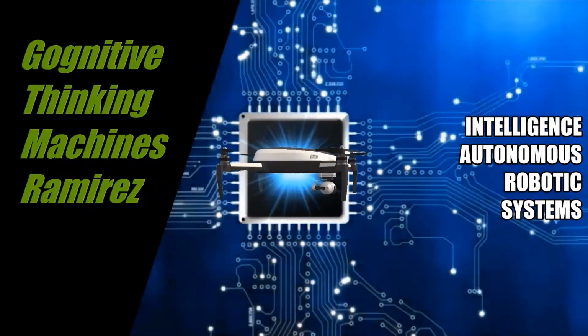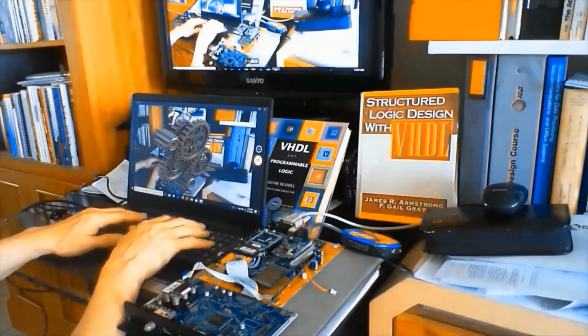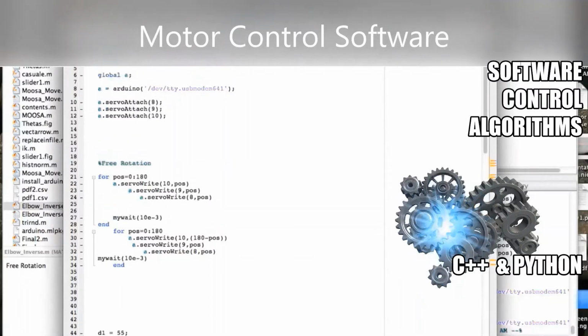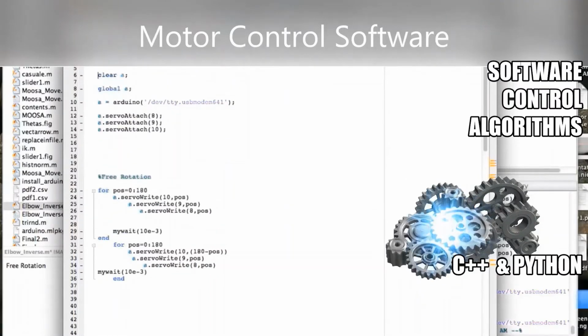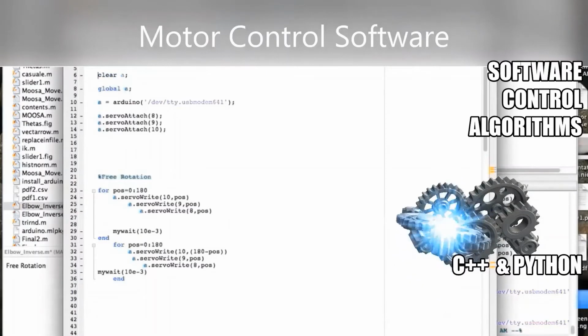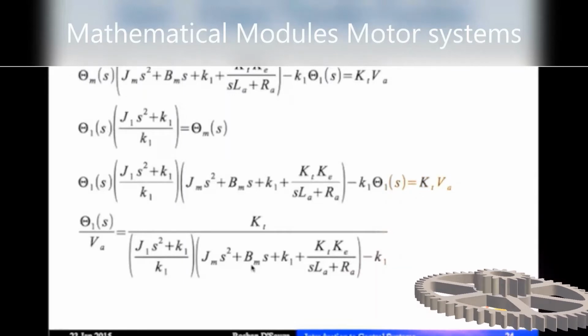Flight control dynamics. Each motor spins in the same direction as its diagonal counterpart and in the opposite direction of its horizontal and vertical counterparts. The rotors on each motor produce a thrust and a torque around their center of rotation.